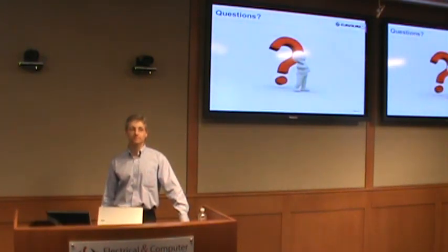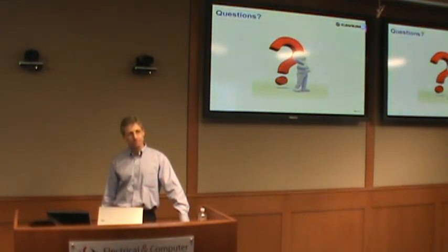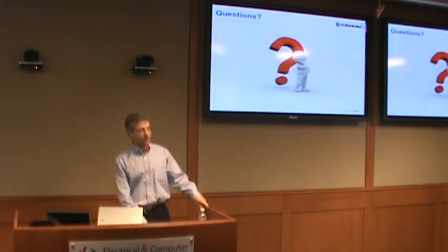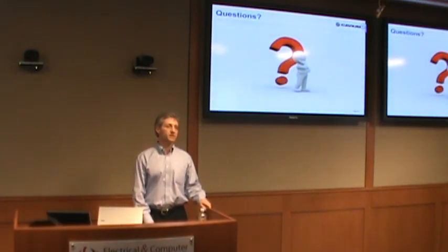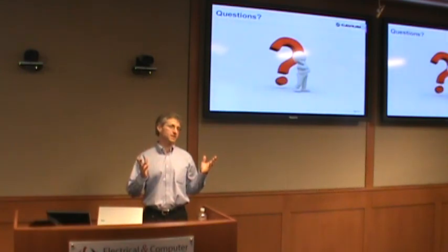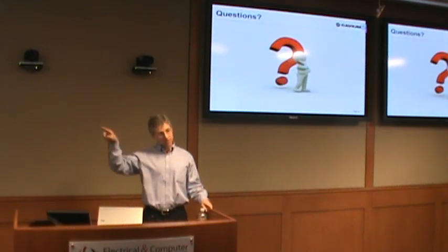Okay. So I'm curious about this don't write back thing. So are you saying that a core might write some data to the cache and create a dirty cache line? Yep. But then somehow you know that you're not going to use that again. Yeah. So for example, that core, when it writes the data to the cache, might be creating packet data. And it may know that, furthermore, that packet might get sent out of the chip. And it may be that once that packet is sent out of the chip, we know, hey, I'm not going to need that packet data. So the core writes it, and then the hardware is what actually sends the packet out.